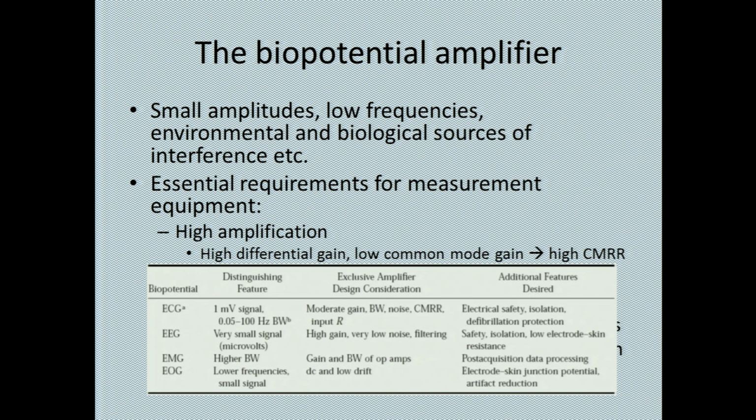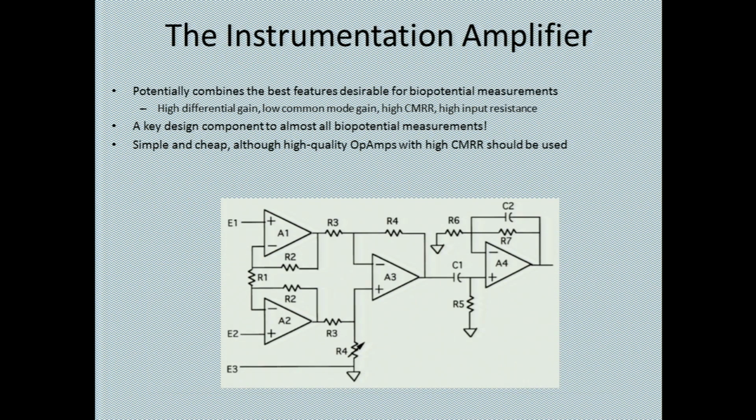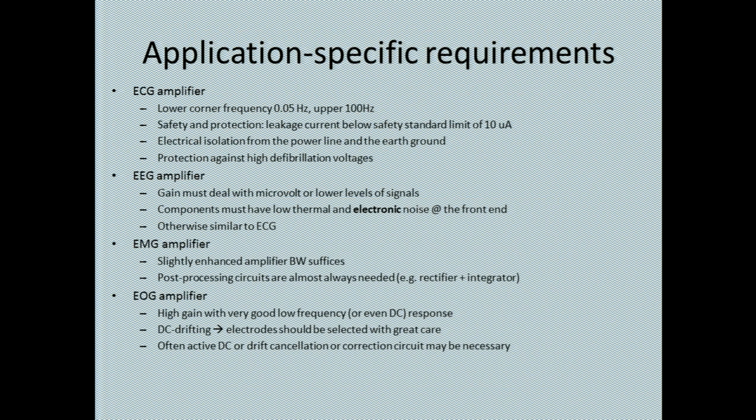Up to this it is electrical, we can build whatever. So you have to have short leads, nicely sitting, neat looking. Let me see how you build, because that will contribute to your noise and pickup. Each wire will be like an antenna, it will pick up everything possible. That is where you come into the picture.